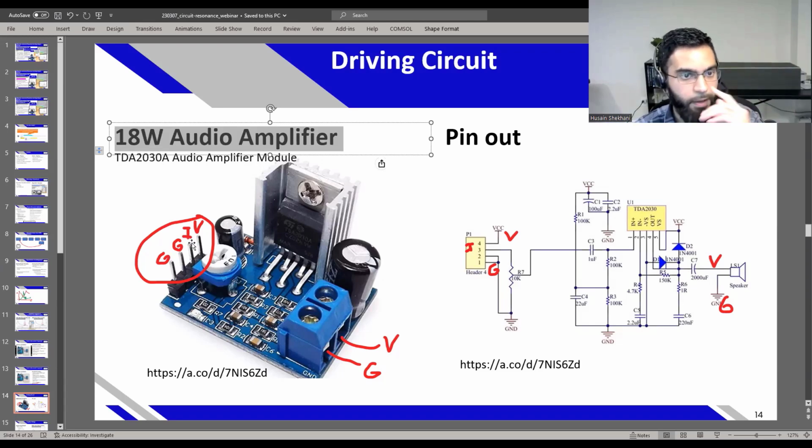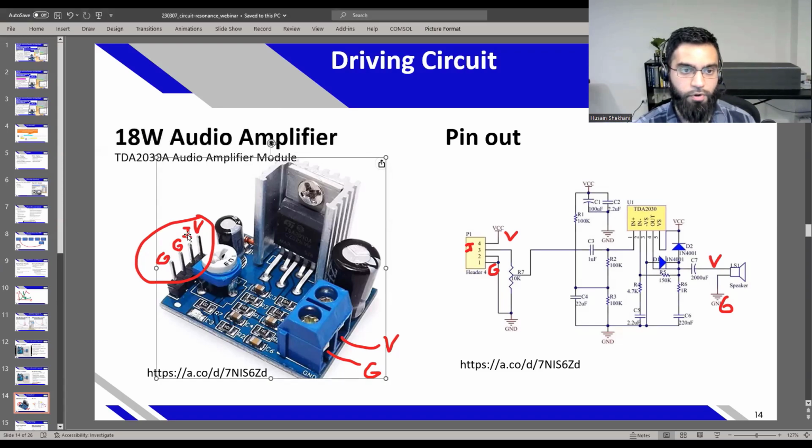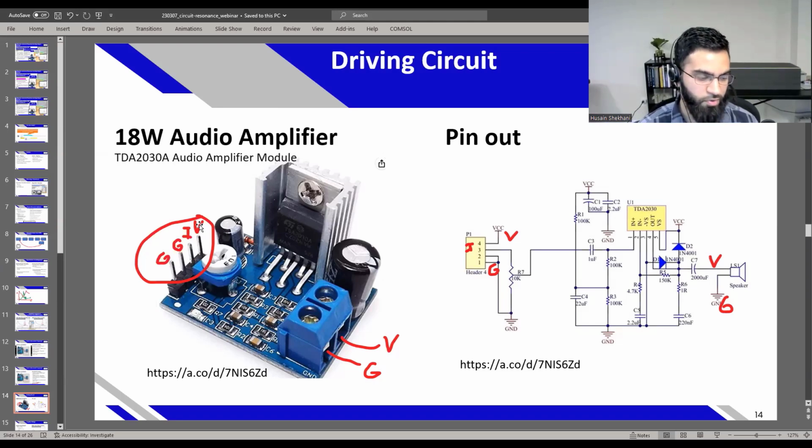And so here are the pinouts. I'm just going over this so you folks have no problem replicating my work. And there's another comment. I will get to that right after I finish this slide. So here are these ground pins which are connected. This is where you put your input, this pin, and this is where you put your voltage. I used a rechargeable 9-volt battery, which charges via USB, so it doesn't provide 9 volts. Strangely enough, it's more like 7.5 volts.